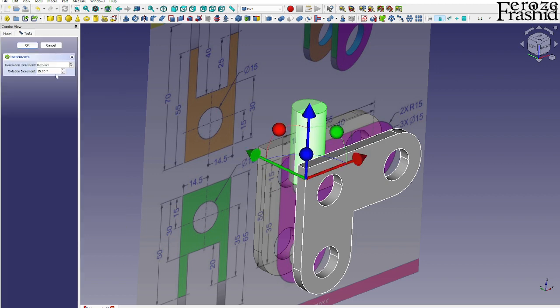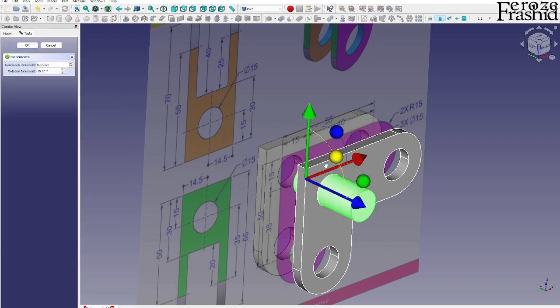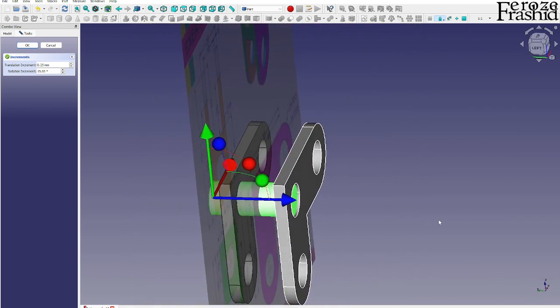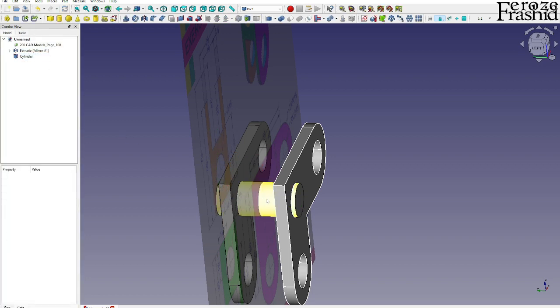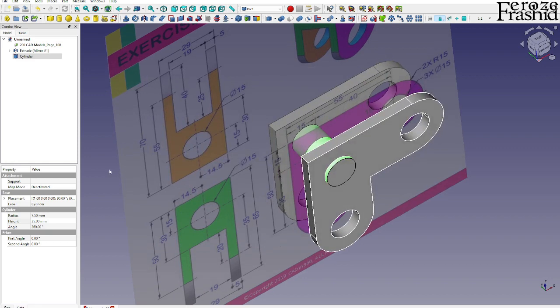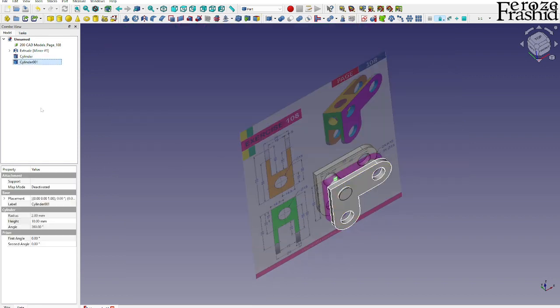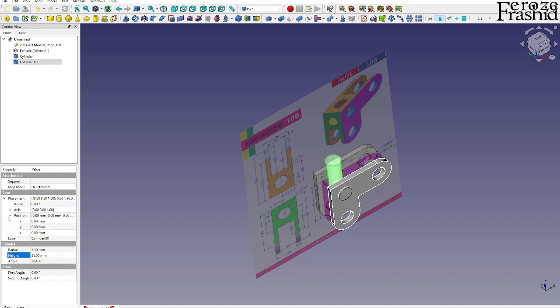I want to transform it to face it like this, so that matches with our hole, and let's bring it back, push it down there. So that is our first cylinder. I want to make another cylinder. Obviously it would be the same diameter and then height would be say 35, but I want to bring that z to -16.